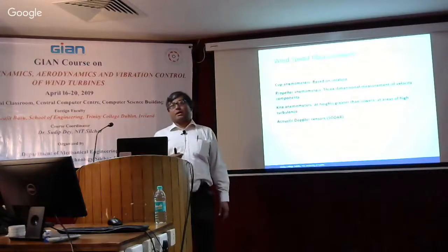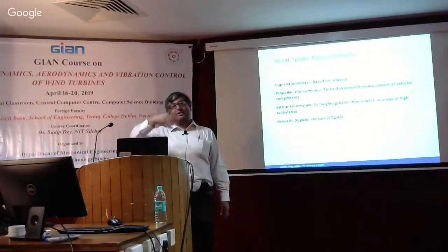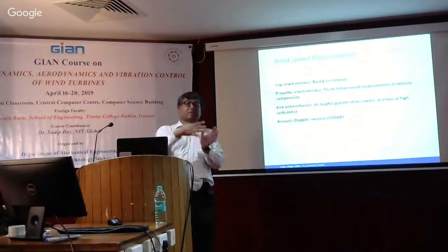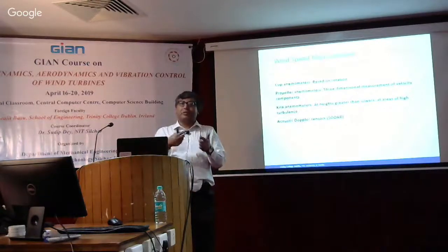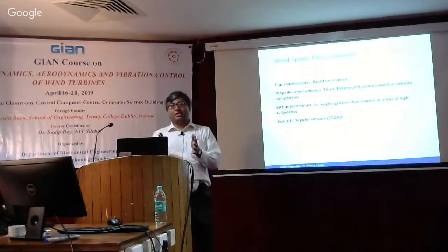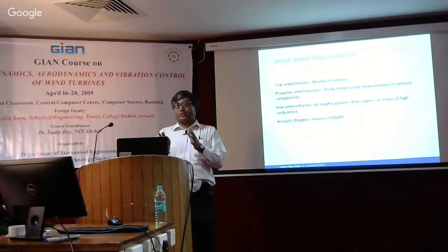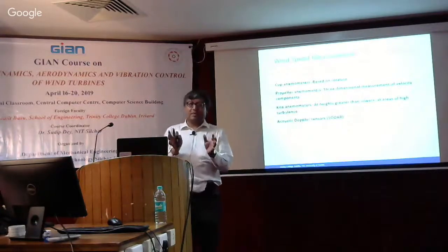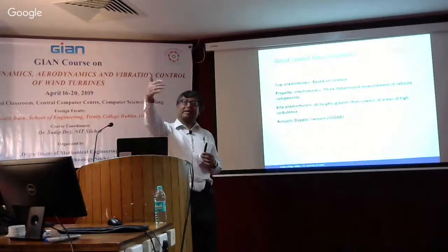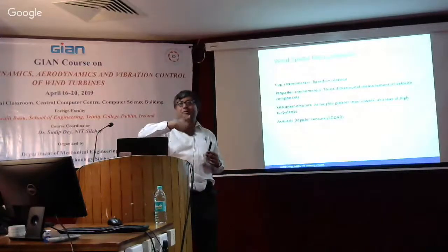measurements, and what people are doing is that upstream velocities are being measured, and then based on the analysis and forecasting, they are predicting what the wind speed is going to be after a certain duration of time, and they are using it for control. That gives us information in advance of the wind coming to the turbine, and that way we are accounting for the non-causality in controlling, because we don't know what's going to happen in the future, but based on wind that's there already, I can say what's going to happen after, say, 10 seconds or half a minute.